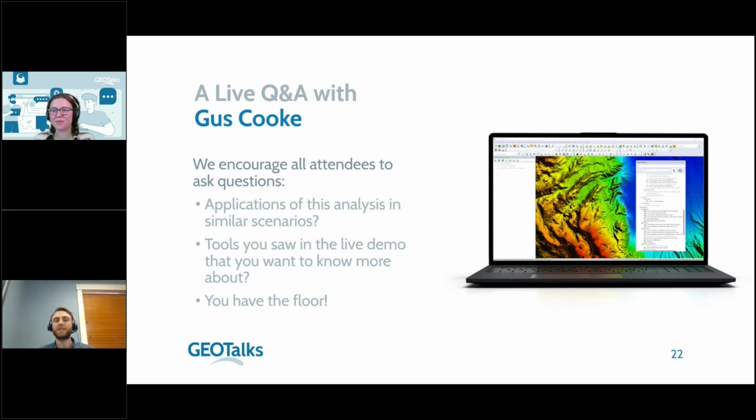I was just changing the date and time range and then running it basically 4 times, twice for each site. And there is a Global Mapper script command for the solar shadow analysis tool. So that is definitely something that would benefit from being automated using Global Mapper script language, especially for that part of the process. But generally all of this could potentially be scripted for sure.